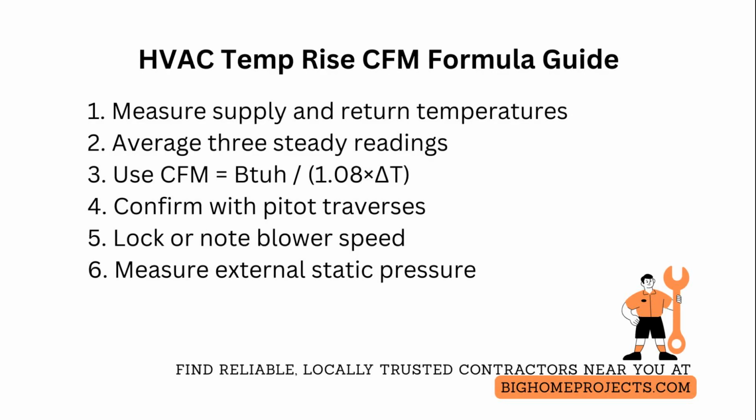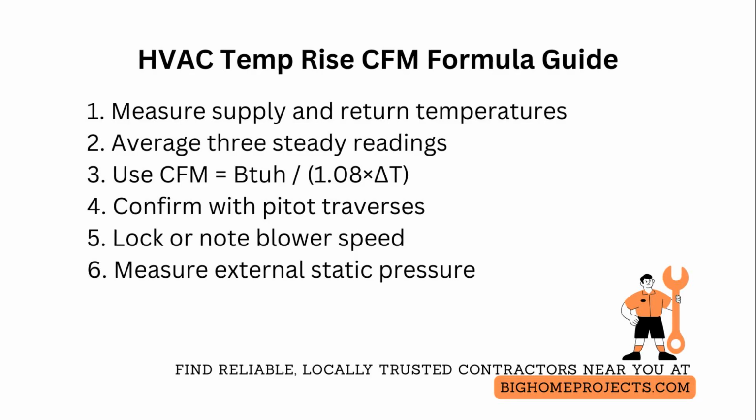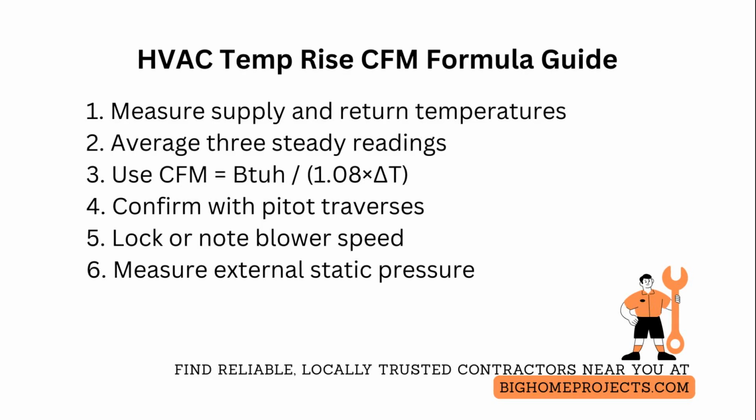Use a manometer or Pitot traverse to confirm duct velocity if CFM discrepancies exceed 10%. A single point velocity can mislead in uneven flow profiles. Perform a minimum of 5 traverse points across the duct and calculate the area weighted average.